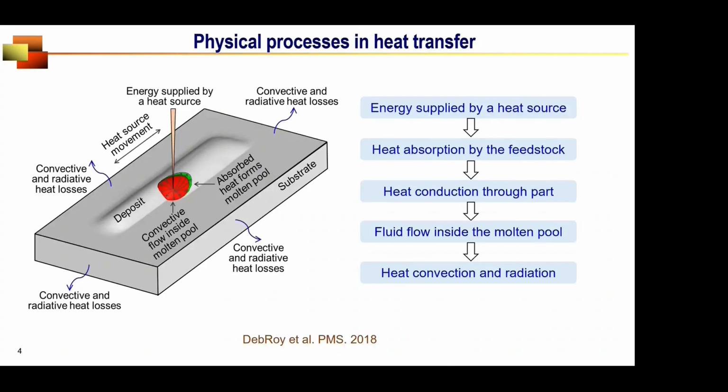We have an energy source independent of which process we talk about, whether it's PBF, powder bed fusion, or directed energy deposition processes. The material interacts with the heat source, it locally melts, the heat source moves, so there is a temperature gradient. And because of this temperature variation within this fusion zone, a liquid metal flows. It is not a stagnant metal, and also the pool is moving.